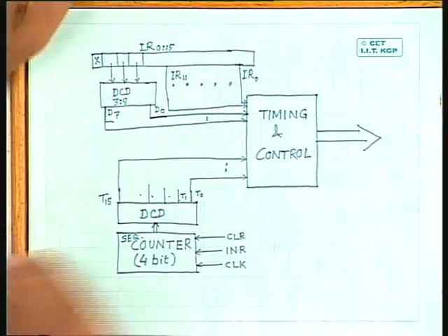Now the thing is, what will be done initially? You all know that whenever you switch on the power of 8085 or you reset 8085, the program counter of 8085 becomes 0. And the 0th location in the main memory must contain an instruction. If it does not, then however sophisticated hardware you design, that microprocessor based system will never work. Why? Because whenever you switch on the machine or reset the 8085, the first time state generated is time state T0. That means initially the sequence counter will be set to state 0.